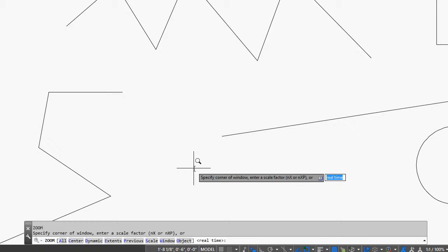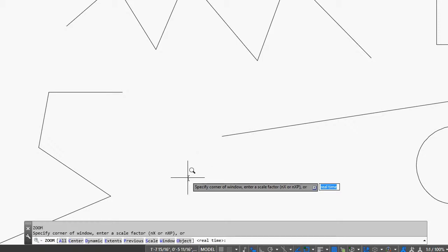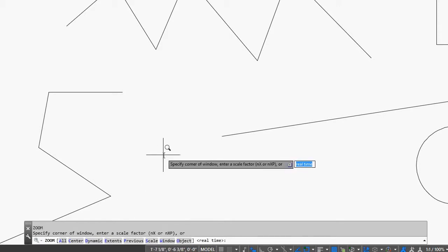So for example, I want to do a zoom extents. I already typed in Z for zoom, and now I want to type in E for extents. I know that I need to type in E because that E is capital. A lot of times you'll find it at the beginning, sometimes you won't. There might be times where the capital is in the middle of that subcommand, and that's fine, but that's AutoCAD saying you have to hit that in order to get the extents. It doesn't matter if it's capital or not, this is just an indicator that that's what you have to hit, and hit enter.